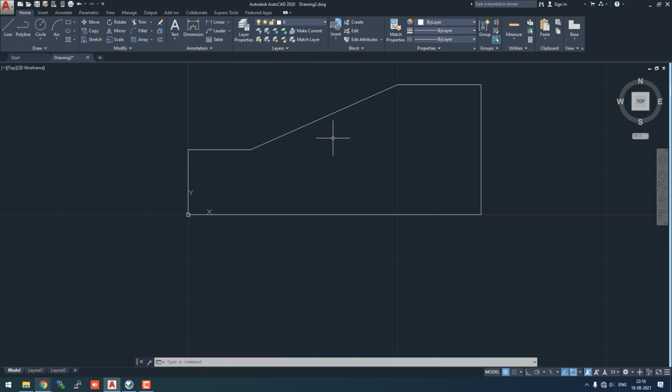Now, as we have seen, there are two soils, soil 1 and soil 2, so we have to create a division again. This division we will create by selecting the line tool, extending the line and joining it with the vertical boundary, and doing that we have created the final geometry.